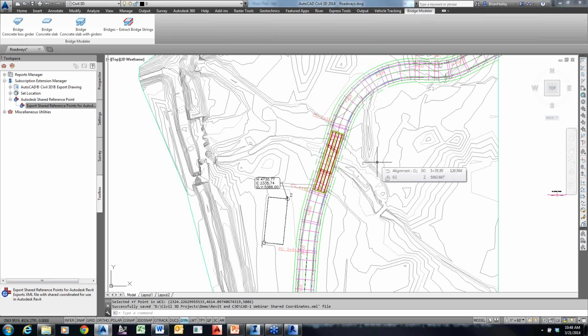So you want to understand how they're doing it so we can request that information back from them and say, hey, I need something that's a little bit more complex in here. So two things we're requesting: a smaller area, a smaller topography, so I don't have 5 miles or 10 miles away for that particular topo surface that I'm getting, and two, right in the area where I'm talking about, break that down even more, whether it's where my building pad is, or my road, or my embankment. This is going to make your topo surface a little bit easier to handle inside of Revit.